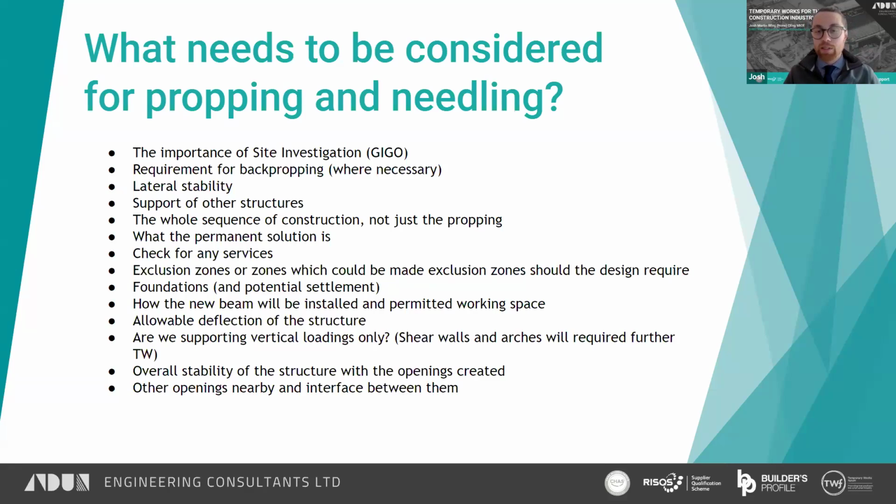Who's taking responsibility for that? And also, what about the sequence of other openings being made and the interface between them? This should be coordinated by the site team or the temporary works coordinator, to make sure that the design solution, the engineered solution, takes into account that there are other openings and holes in the structure at the time when this activity is being carried out.